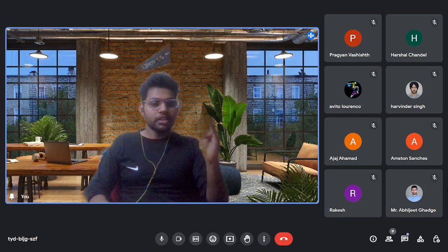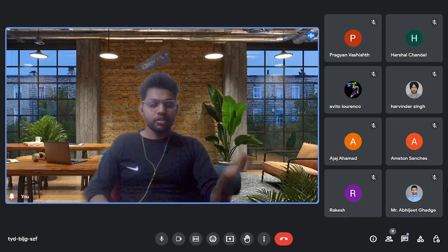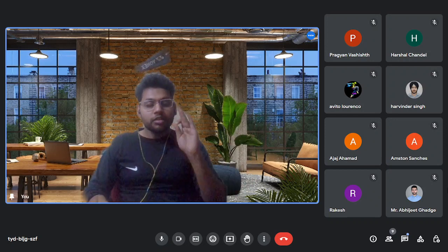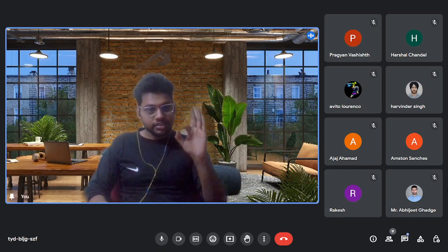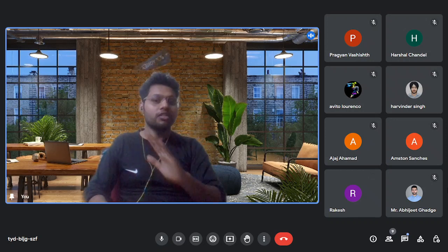What he said, the safeties of the auxiliary engine are like low lube oil pressure trip, high jacket water alarm, that will be discussed later. He said oil mist detector also, but the problem is the oil mist detector is a type of safety for a two stroke main engine, not for an auxiliary engine.